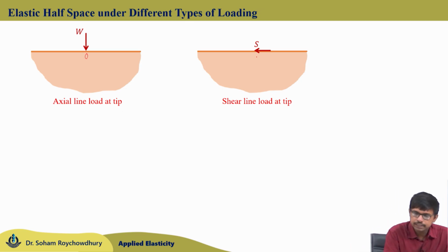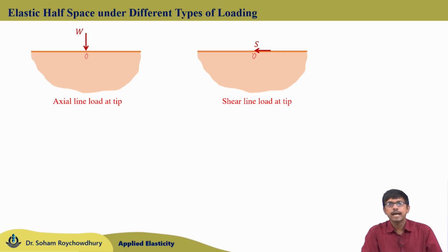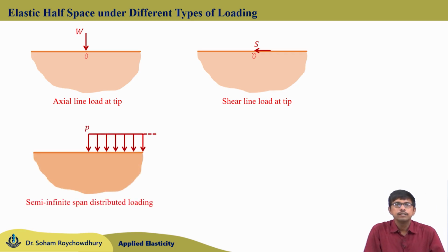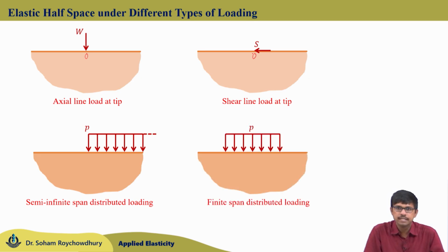Now, moving further, instead of the line loading acting at a specific point O, which we are defining as tip or origin, we may have the distributed line loading acting on the semi infinite body or elastic half space. The span of that distributed normal load may be finite, or it may be semi infinite as well.